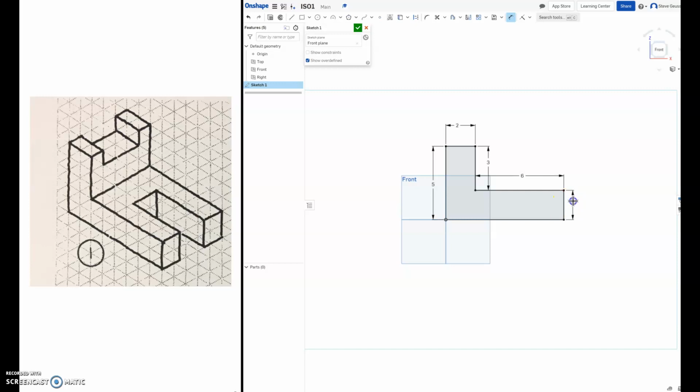But what you might see is that I can't change this. Okay, this is a driven dimension because these are perpendicular, and in Inventor lots of times on other AutoCAD programs. That's why this is not looking like the same dimension. It's kind of in a shadow because it's driven. If I've gone 3 and I'm perpendicular, I can only go 2 more if these lines are perpendicular. That's a driven dimension.